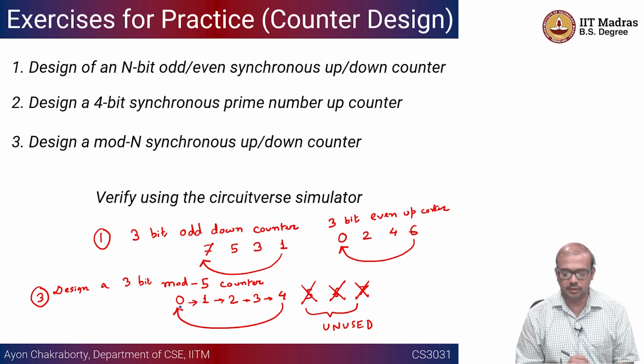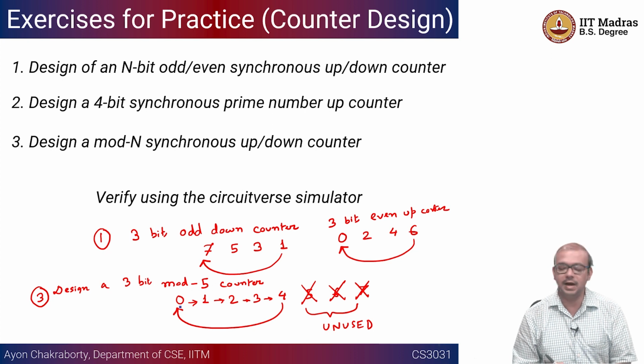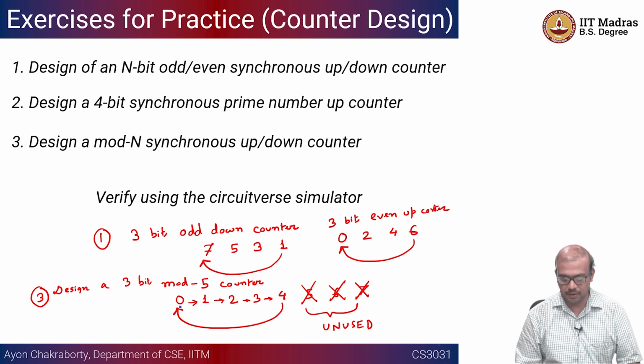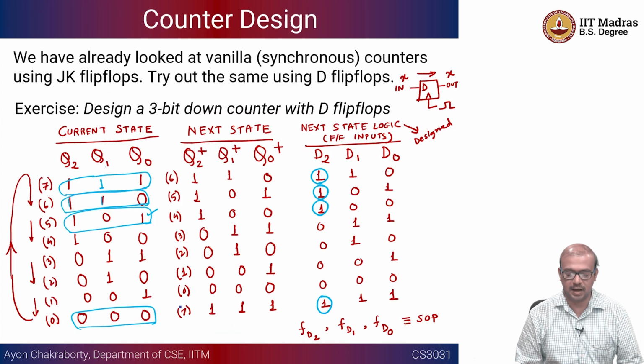Okay, so this is also something that you can do either up counting or down counting depending on in what direction you want to count, but the recipe that you want to know from here is the same, right? That's why we told you in the very first class that we are going to learn some design principles. Any kind of sequence or any kind of counter that is given to you, you should be able to design using the simple recipe of the state transition diagram table.